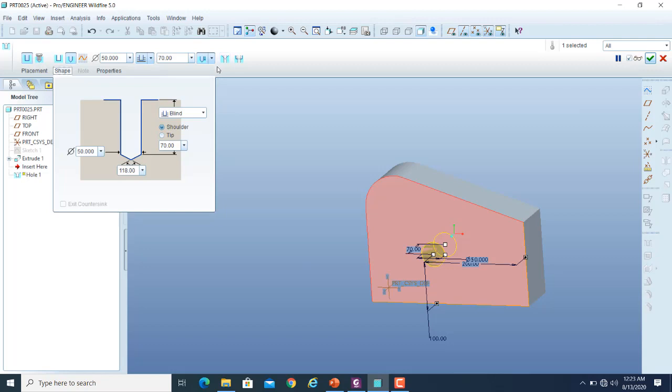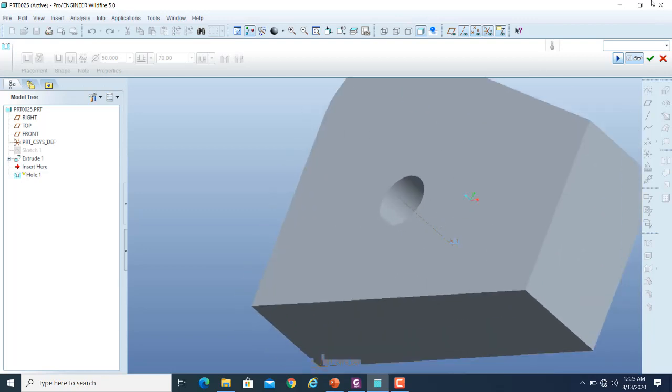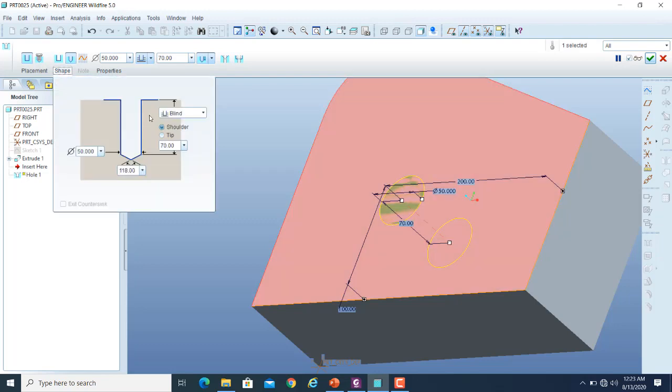In the last we have two further sub options for the cylindrical one, and that is the counter bore option and counter sink option. So right now hole के ऊपर अगर आप देखें तो you have a simple flat hole like this one. So if I want to use the counter bore option, so I can use it. Then I look at the shape also. So if I pick on the counter bore, so it will put counter bore hole over.